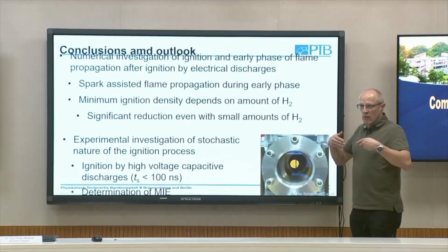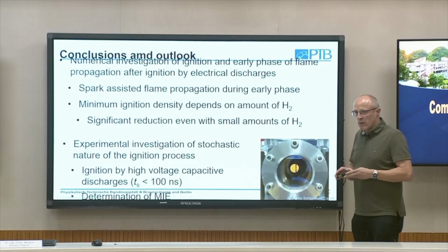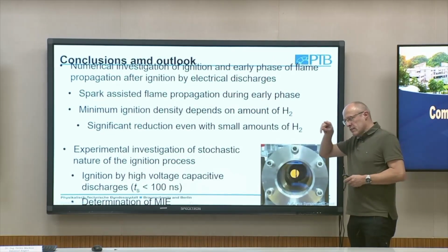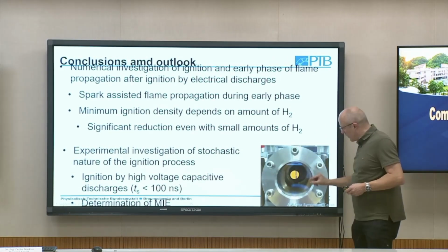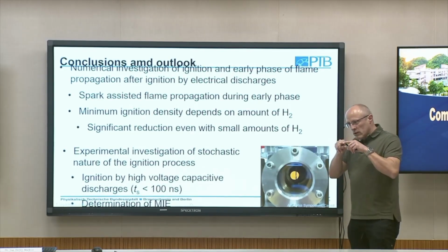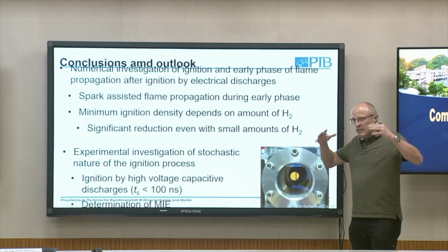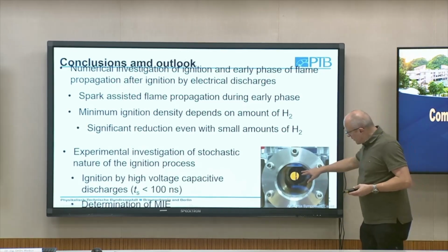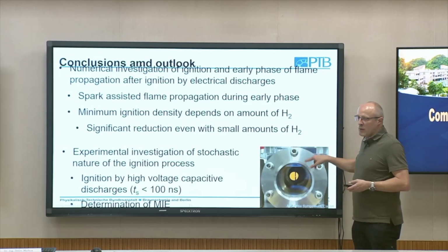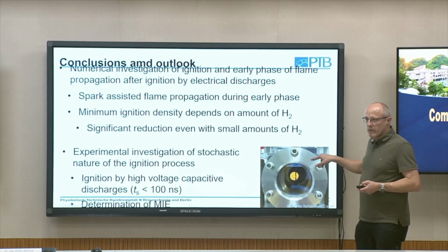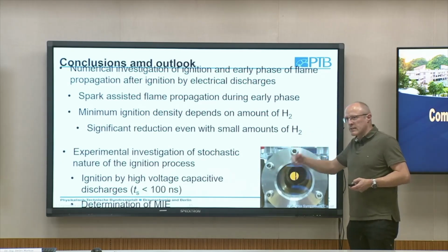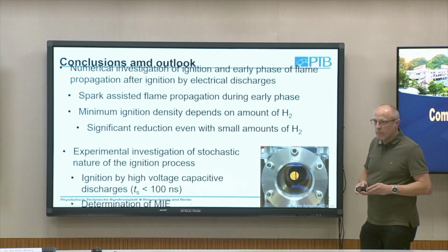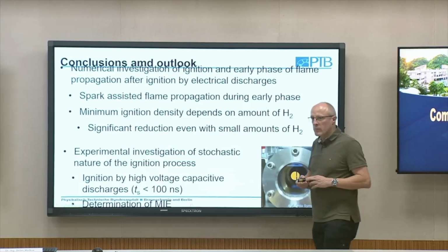You see more or less an overall global flame velocity. So you have an expansion of the hot gas kernel, and you have, of course, a curvature effect. You have at the beginning a very small flame ball, which then increases, so the curvature reduces. But you can measure the flame front as a function of time, and then calculate from this the laminar burning velocity.